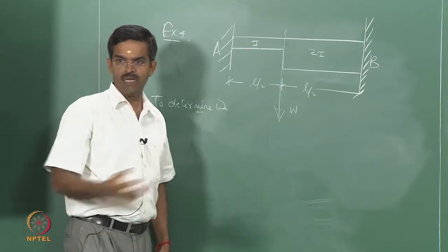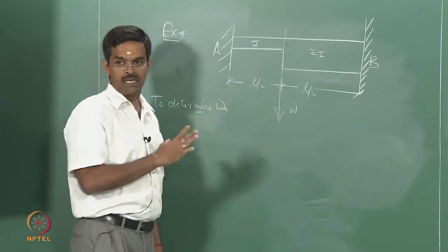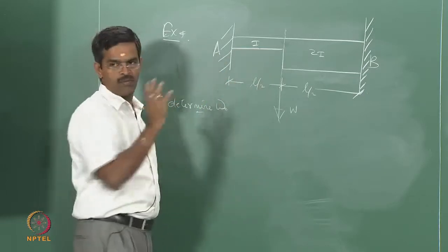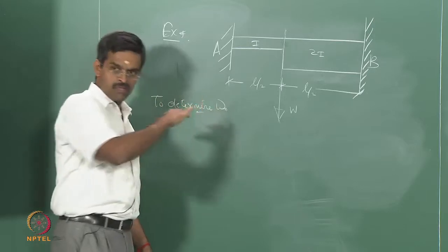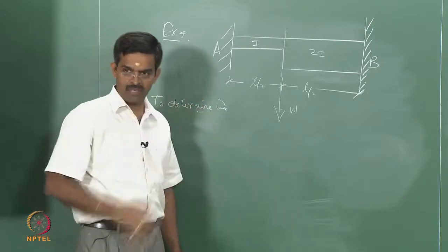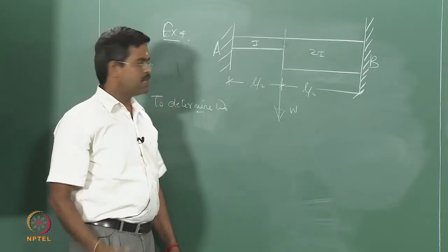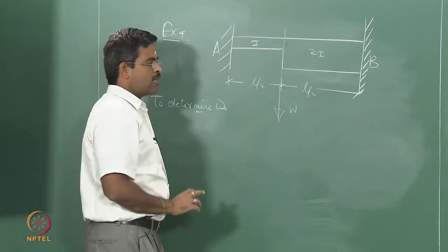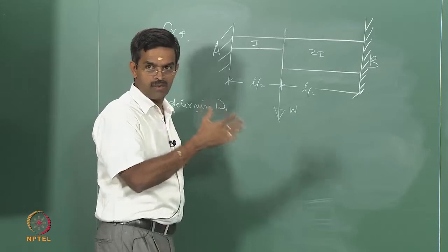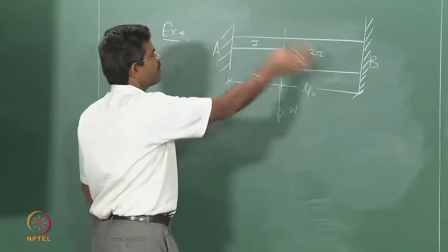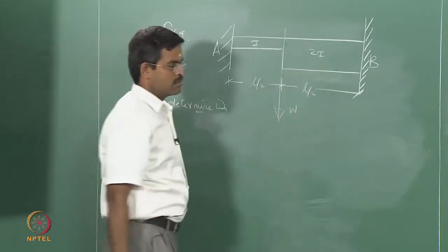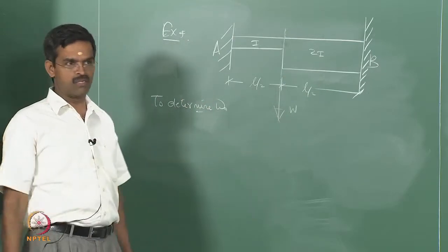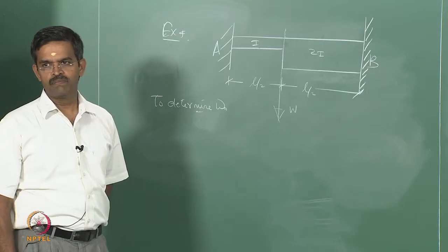It should not vary widely. So, you have to have a hand understanding of whether you can model this in simplified form and find omega n in simplified form. We will start with this, and move on to accurate levels later. The worst thing is to go only for the accurate level, never bother about the starting level, and always depend on software. Whatever answer you get, you will always say the beam is vibrating at a frequency of 22 hertz, whereas the real frequency will not be 22, it may be 220, we do not know actually, and we make a mistake in design and the system will fail.